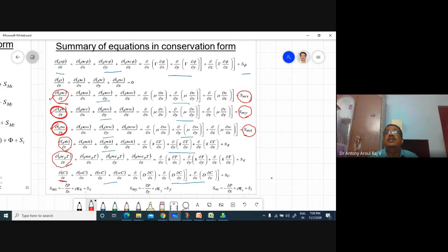So what you can do is split that momentum, because even momentum is a vector. The source also can be a vector. That means it will have the i-th component, the j-th component, and the k-th component. So in the place where you have the fan, wherever the flow is there in the predominant direction, you can split the momentum into 3. You give it in that particular direction, and whatever direction it is coming, you can give it in vector form. But you have to split it into 3 components, and then give it.